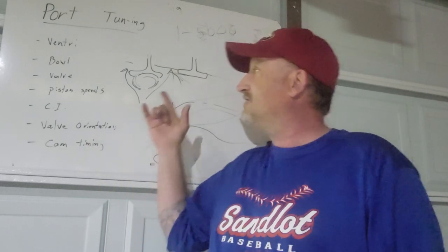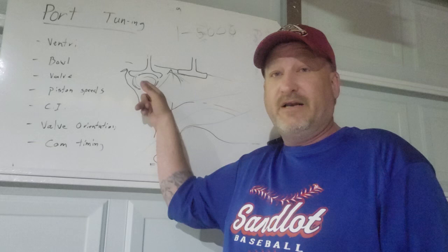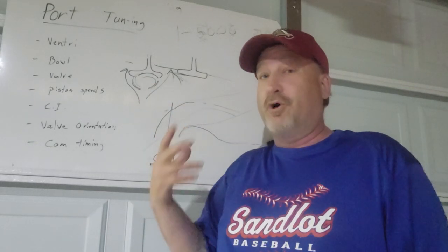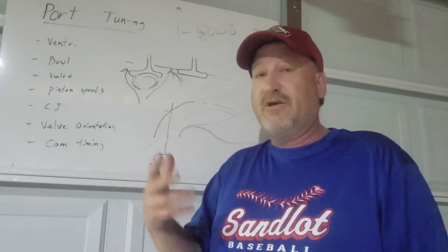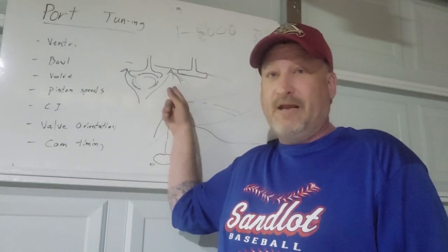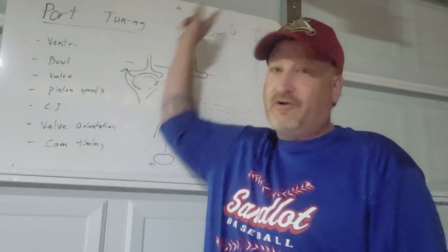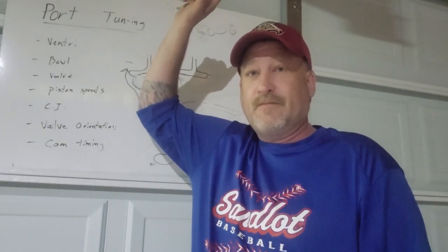It means that it's actually allowing the gases to be burnt precisely where it needs to be. None of those burnt carbon molecules of the exhaust gases are sticking to the combustion chamber. They're being burnt efficiently that by the time they reach underneath the exhaust valve, they're going right out the exhaust pipe.